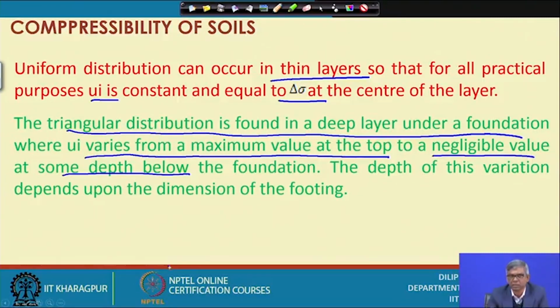Because immediately after loading the pressure will be more on the soil, and as we go deeper and deeper the pressure will be less, and this pressure will be countered by the pore pressure only. So near the surface pore pressure will be more, and at greater depth pore pressure will be negligible, and sometimes it will become 0.